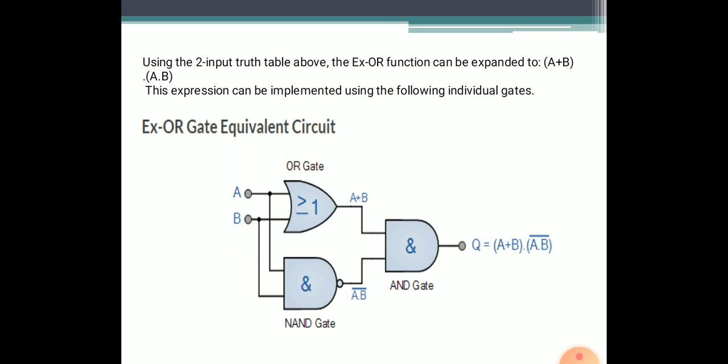When searching for a PRN sequence or a specific bit pattern in a very long data sequence, a series of XOR gates can be used to compare a string of bits from the available data sequence against the target sequence in parallel. Then the number of zero outputs can be counted to determine how well the data sequence matches the target sequence. Correlators are used in various communication devices such as CDMA receivers and decoders for channel codes and error correction. In a CDMA receiver, the correlators are used for polarity extraction of a particular PRN sequence out of a combined collection of PRN sequences.